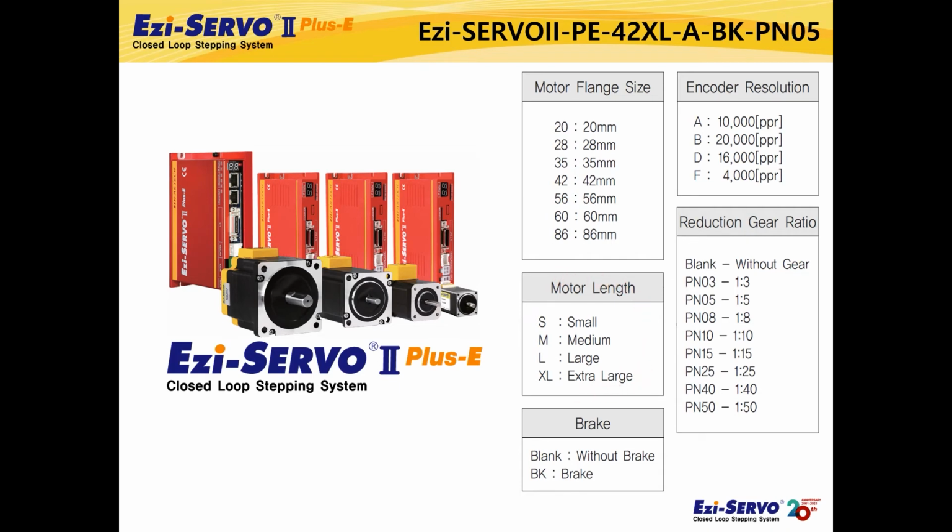The length you can select depends on the motor size. The encoder resolution can also be selected as shown in the table. Gearbox and brake specifications are also available. A gearbox and a brake can be applied from a NEMA 17, 42 mm size motor, to a NEMA 34, 86 mm size motor. Gearboxes are planetary gearboxes, and gear ratio can be selected as shown in the table.